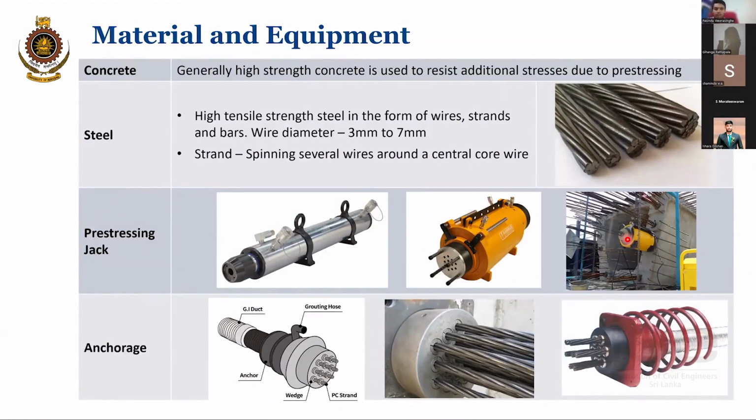Sir, during post-tensioned prestressed concrete, when we insert the duct and grout, do we keep this duct permanently, or do we remove the duct? We have to keep it permanently. We are not using any expensive material for the duct. It is like the conduit pipes that you insert in the slab to put the electric cable, something like that.